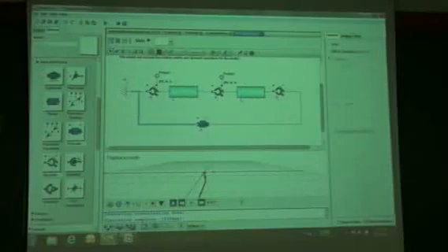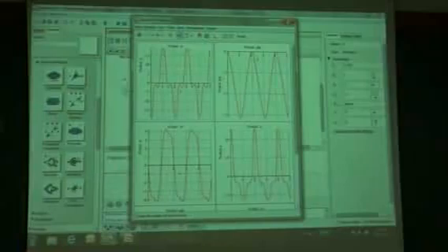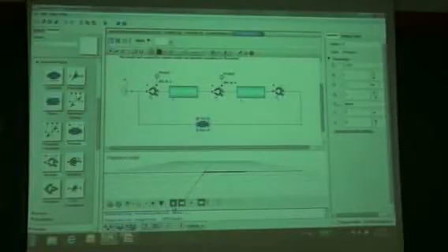So a prismatic joint is just a joint that constrains this point to move along this x-axis. Selecting on the x-axis. So it's constrained to just move along the x-axis. And so if we run this, we now have the start of a slider crank mechanism.